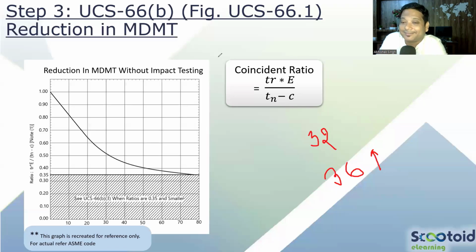We take the advantage, that is very clear, but how? Our normal logic says that higher thickness means problem. But it also depends upon the stress which is getting generated. By having higher thickness, the stress generated inside the material is less. And for that reason, you are given that credit. Make sense now? Because the stress is lower by providing the higher thickness, you are getting advantage based on that.